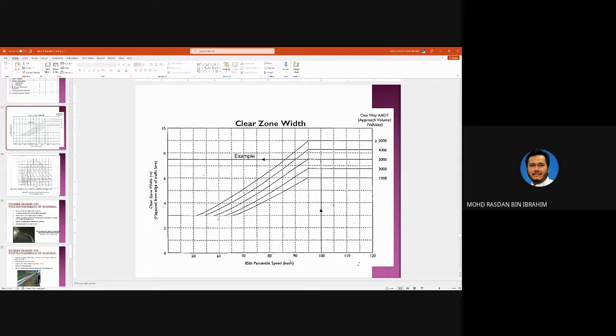Okay, the most common speed. There will always be that 15% that is higher. We do not take into account those people. We assume that those people are the crazy ones that normally will speed higher than the speed limit. So we only cover 85th percentile speed.